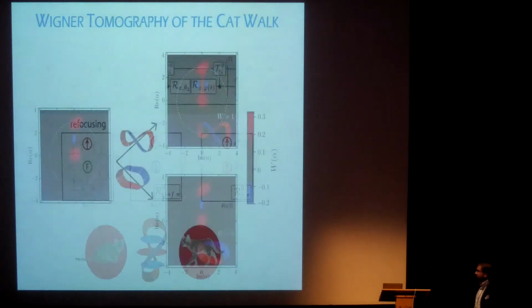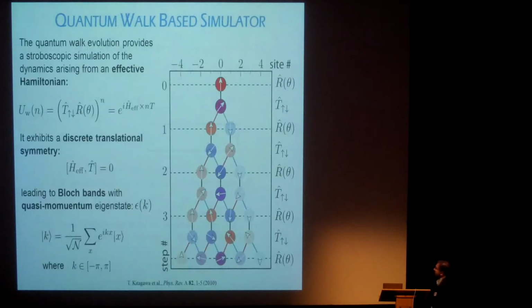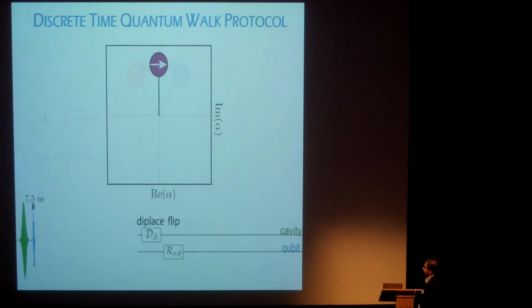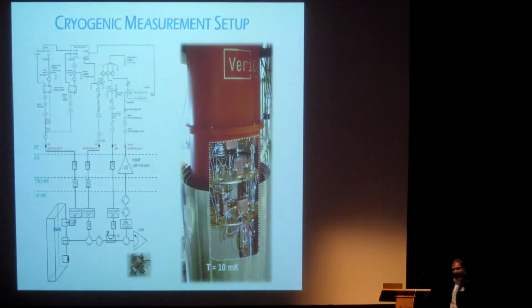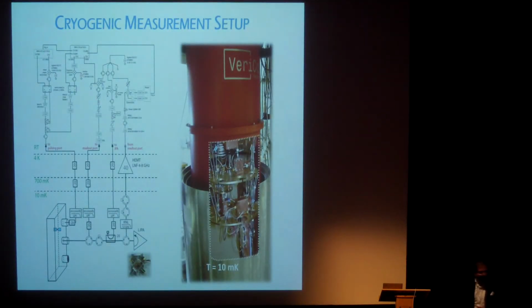A good way to think about that for superconducting folks is to go back to this diagram, which is here. In particular, at the moment, for us, quantum information has to travel from one box to another box, and that's problematic. So if you like, the quality factor of the cavities is extremely high. The losses on chip can be in a regime where they're very small. And in particular, we can be in the regime where most of the information is simply leaking out through the transmission line, which is coupling to the cavity, rather than other parasitic modes. So at the plane of the cavity, everything is good. We can be in the nice Purcell limit where things are coming out.